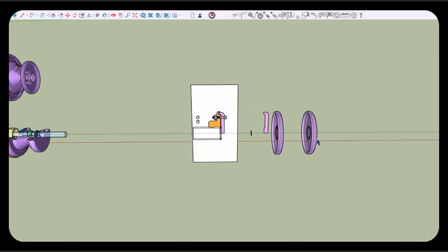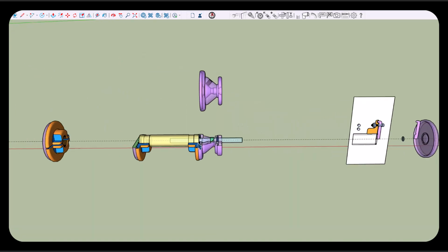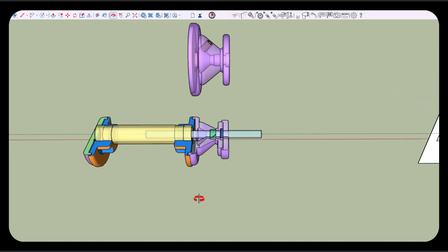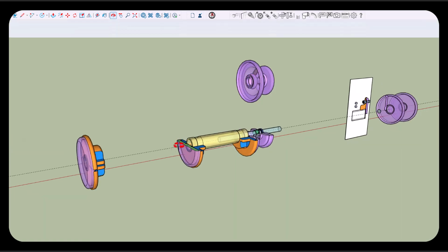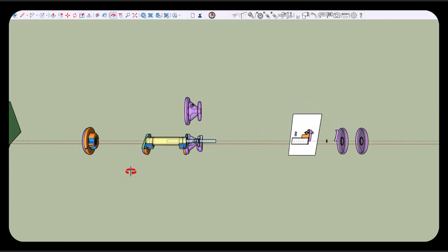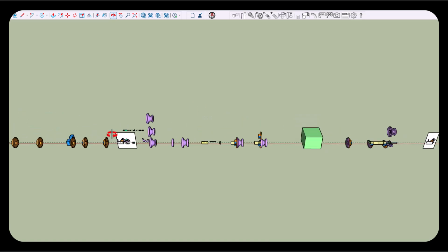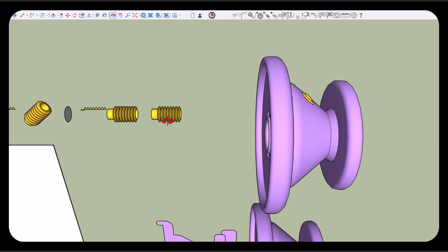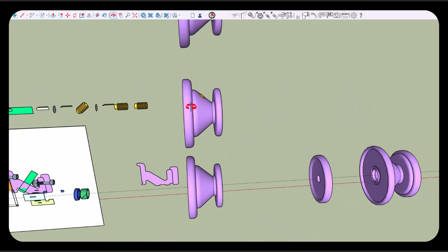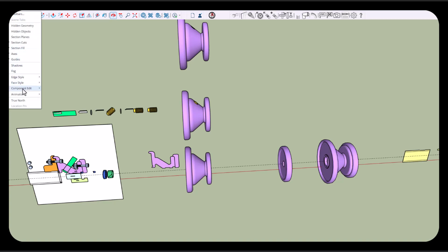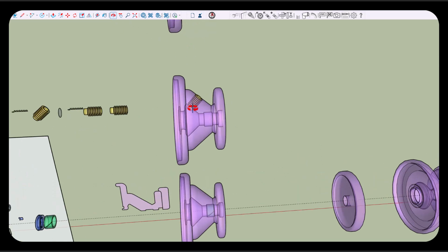So this cap is the cap that goes on the other side, because we have to have this complex cap on this side so we can have a piston rod. But on the other side, it's just sealed up. And the final thing I wanted to show you is that I created this negative version of a 1/8 inch national pipe thread set of threads. And I took that set of threads and I put them in here.